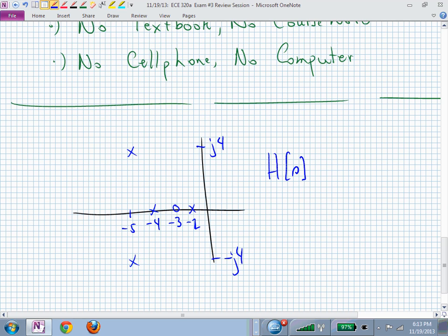So we have 2 plus, how many did you not see the first time? 2. So 2 plus 2, we have 4 poles, don't we? 4 poles and 1 zero. Which of those singularities influence the transient? The zeros shape the transient, but the length of the transient is influenced by the poles. Now, which ones determine or influence the length of the transient? Do we remember the speed? This one, these two complex, what's their real part?